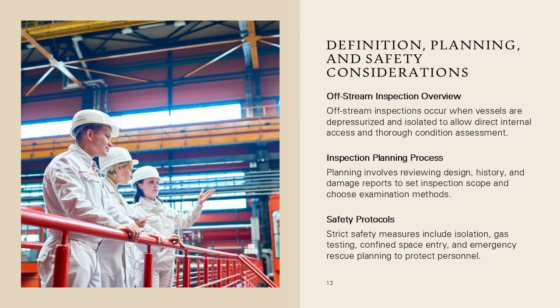Safety is a critical consideration during off-stream inspections. Inspectors must ensure that isolation, gas testing, confined space entry procedures, and rescue plans are in place and followed. Adherence to safety procedures protects personnel and ensures that inspections can be conducted thoroughly and without incident.